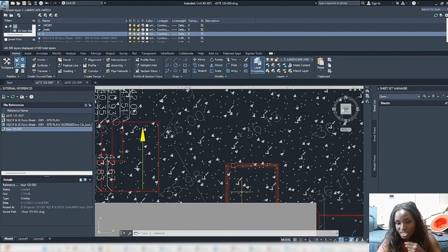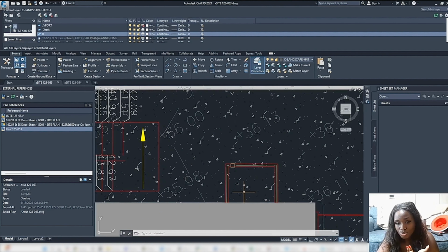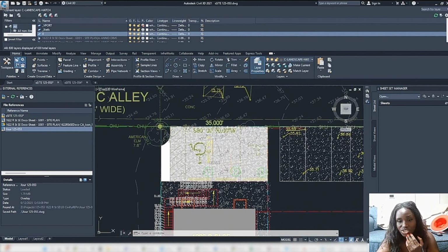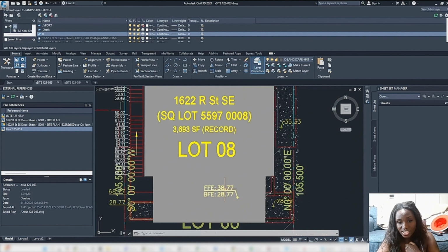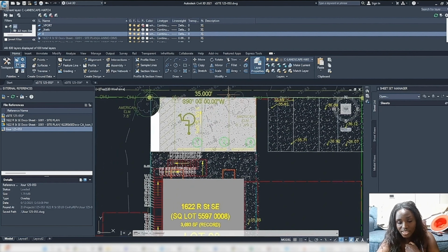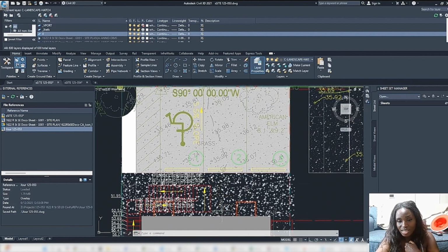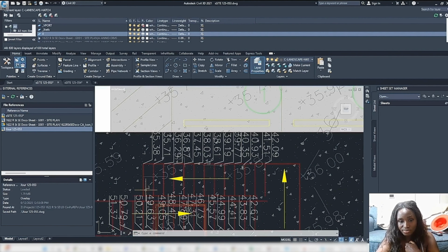This area is going to get constantly filled with water, and water is just always in there because the water is draining towards you. If we do have a situation where here it is lower than this area, that would still be the case. We would still find a way to divert water away. Even if there's a small swale here, water just cannot be hanging out at the base of the building.